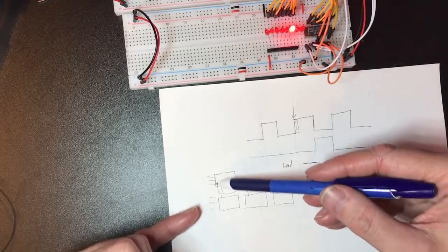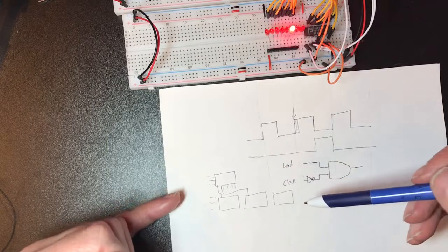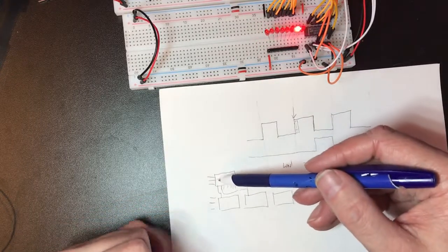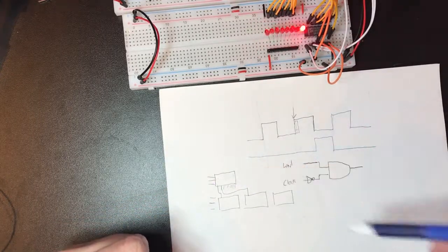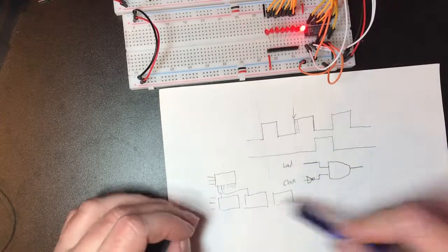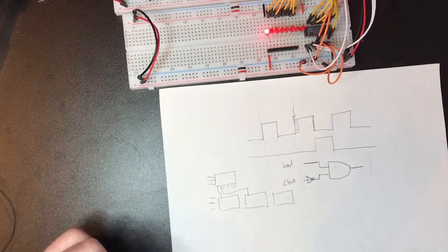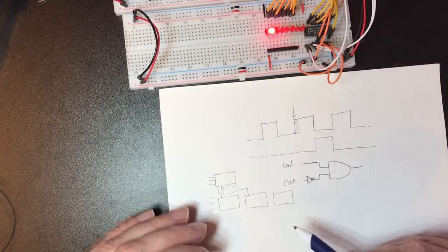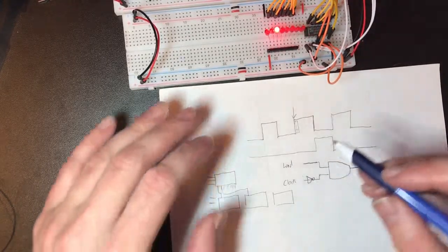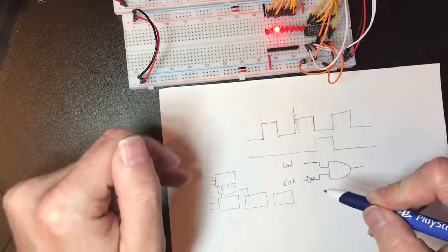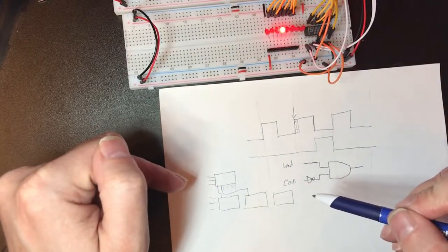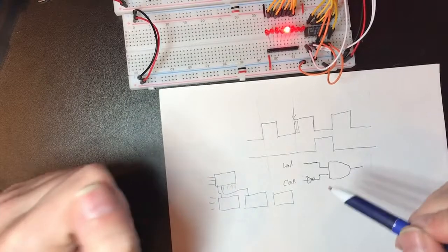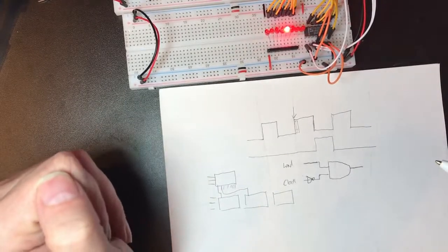Now, we're not going to have anything like that many registers, but there are, in addition to 3 to 8 line demultiplexers, you also get 2 to 4 line demultiplexers, so that would give us 32 control lines. But the situations in which I've been looking at in the processor design, I actually max out at needing 16 control lines from one of these demultiplexers.